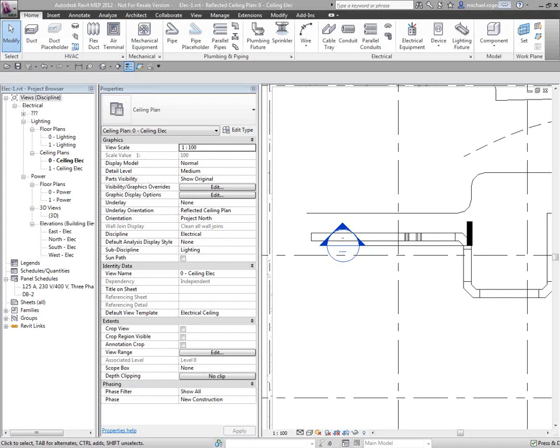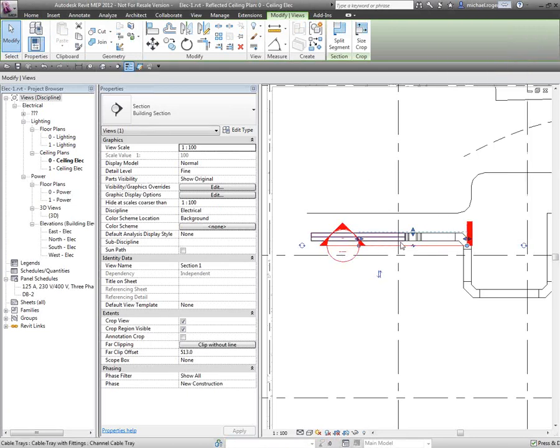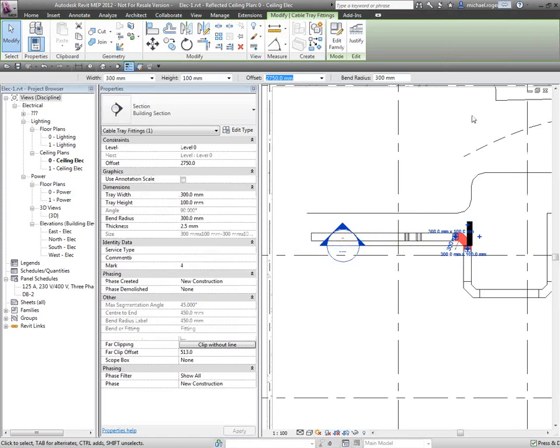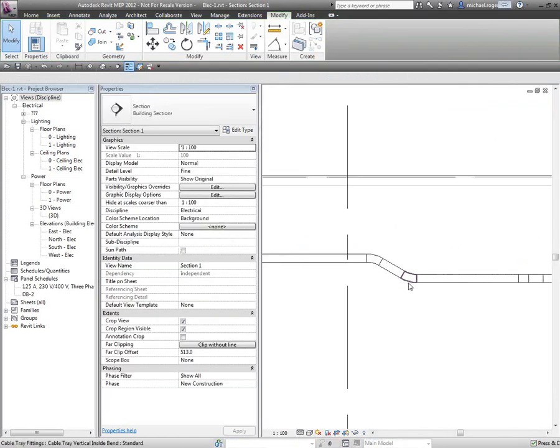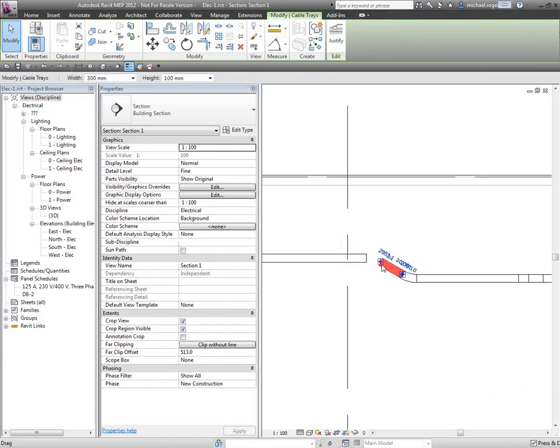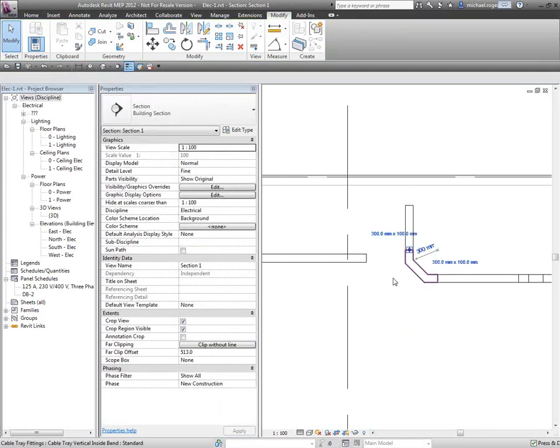Do you know how to draw cable trays at 90 degrees? This is from Judy, in the Brisbane office. To draw cable trays at 90 degrees, it's got to do with your cable tray settings, the actual families that are loaded in. Typically, Revit does everything off the design aspect, but you can always cut a section and draw it up. That's a 90 degree.